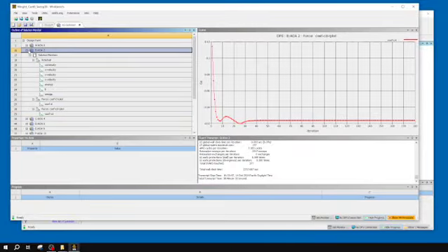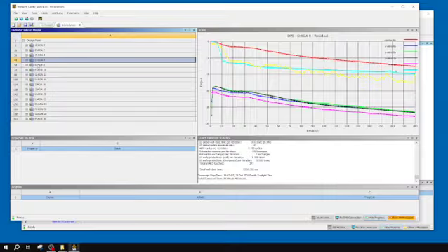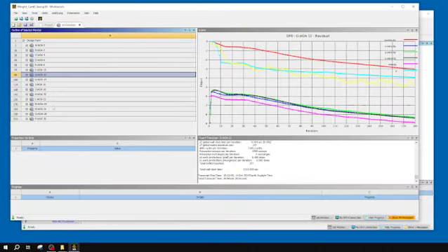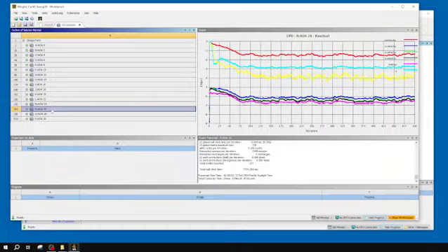Another option you might have, if let's say I pop out to 36. In this case, it never actually converged. You can see here's -3, and we still have both continuity and what's this? Our K term. I'm not exactly sure what the K term is. It should be in the manual if you're interested, but it's just another measure of consistency between iterations.